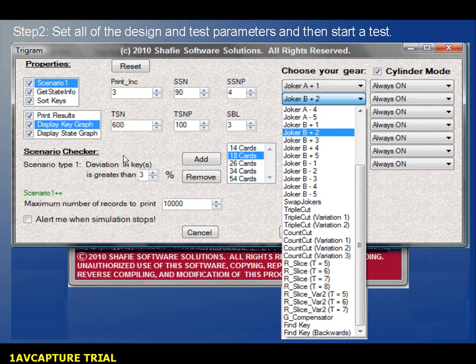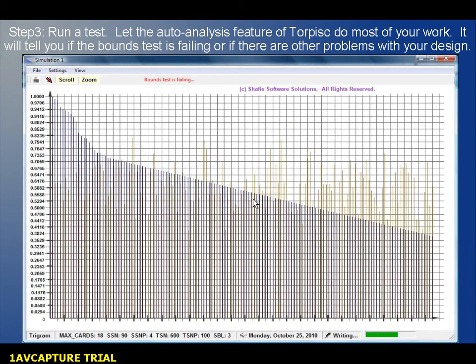Usually the first time you don't need to do any state analysis, so you can uncheck this. And then after you're done using n-gram testing, you can go ahead and retry, but this time with state analysis on. Once you start a simulation, the record numbers with their corresponding key combination and state combination values will be printed onto the screen every time updated results are ready.